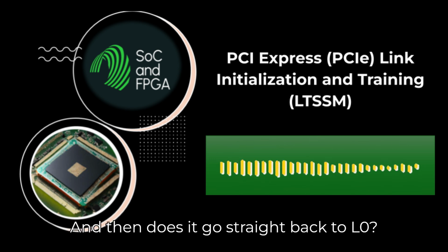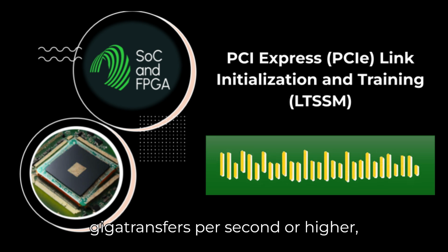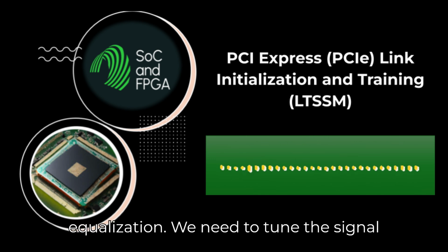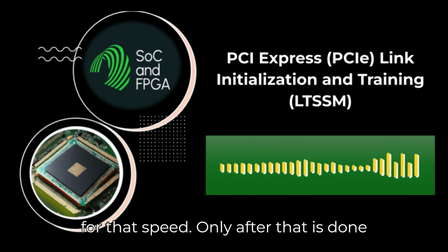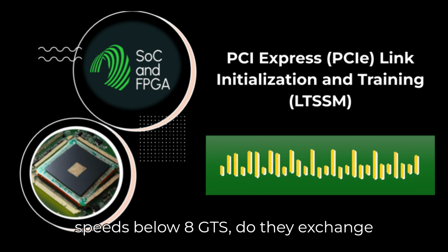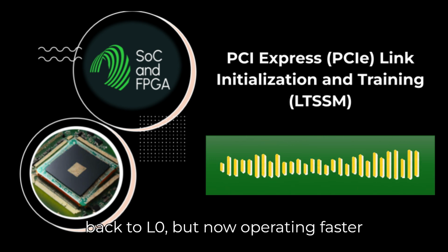And then, does it go straight back to L0? Not necessarily. If the new speed is 8 gigatransfers per second or higher, there's a mandatory detour, recovery equalization. We need to tune the signal for that speed. Only after that is done successfully, or if it wasn't needed for speeds below 8 GT/s, do they exchange IDLEs at the new speed and transition back to L0, but now operating faster.